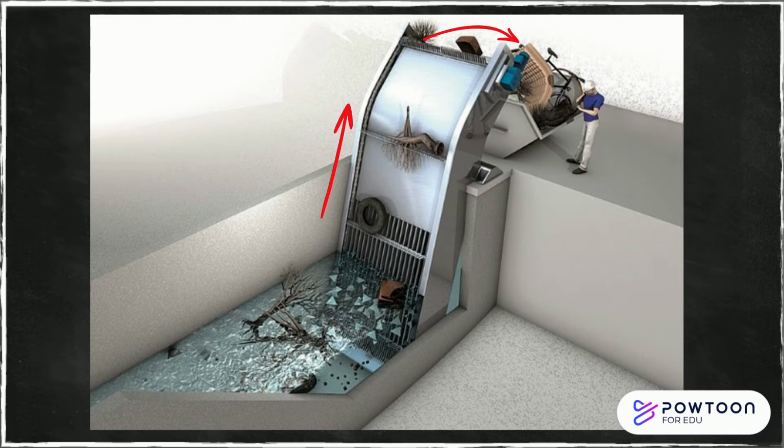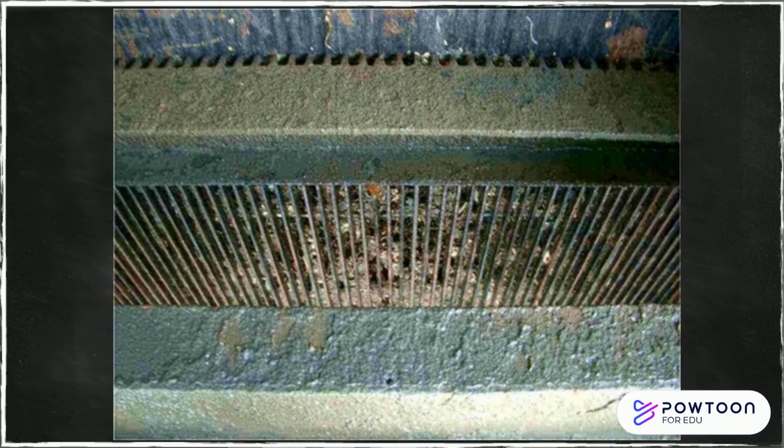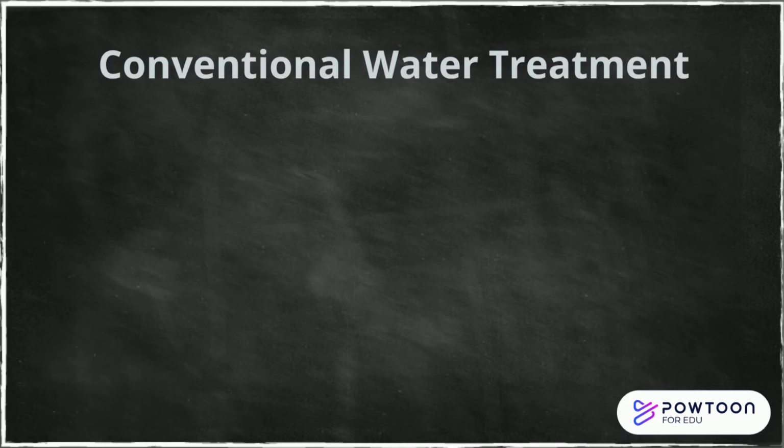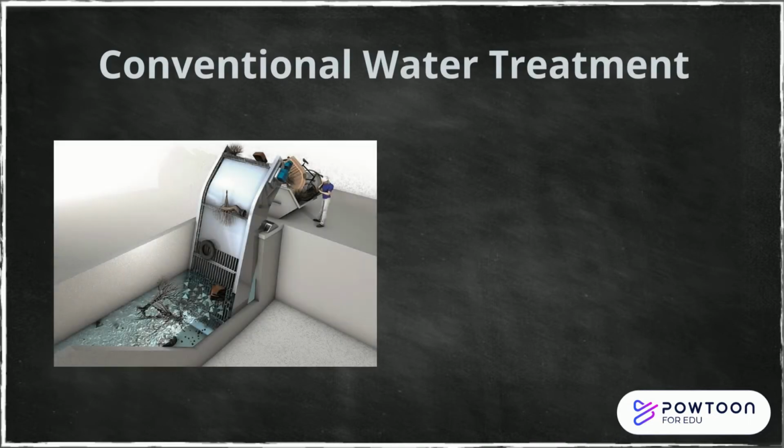From there, water travels through a finer opening screen. The screen catches leaves, wipes, bubble gum wrappers, anything that would be at the intake. This is one type of screen. This is an automated screen. As you can see, there isn't a big dumpster behind it, but there's a small refuse collection, and then the water goes through. So from there, these are our steps that talk about conventional water treatment. So we talked about bar racks and we talked about screens.